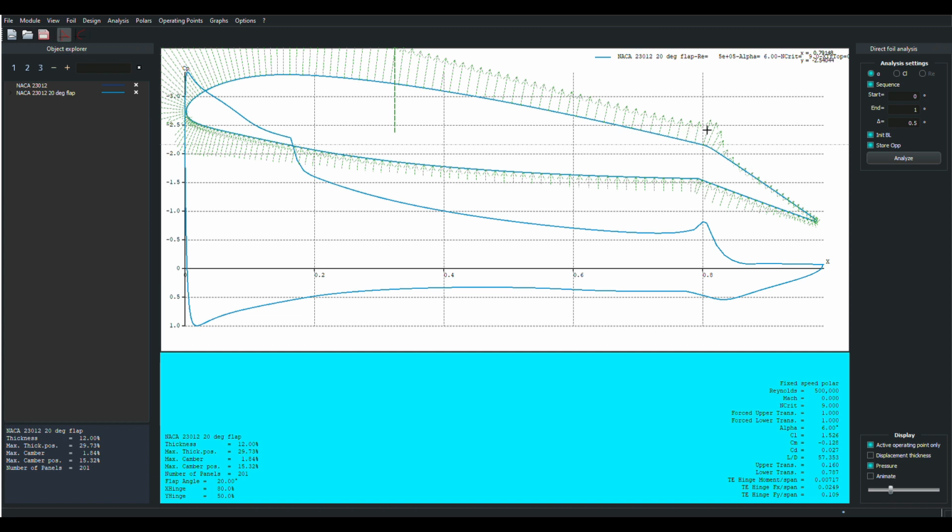And we note that we have this set of pressure vectors here which have a significant spike in them. And that's represented by what the curve does here. Our adverse pressure gradient is here. The pressure is increasing, increasing, increasing. Velocity is decreasing. And then that begins to flatten out. And then all of a sudden, the pressure drops more. And then boom, big recovery and back. So there's a lot going on here at the trailing edge where the hinge is.